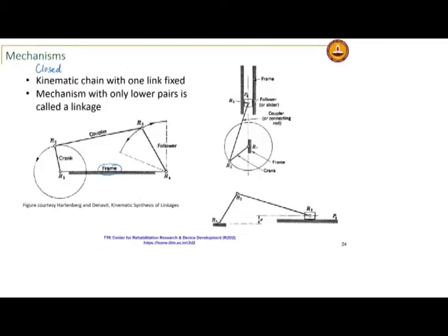The crank can sometimes be used to refer to a link that can make a complete revolution, or sometimes it is used to refer to the input link as well, whether or not it can make a complete revolution. The output is usually called the follower. The crank and the follower are both pivoting about points fixed to the ground.